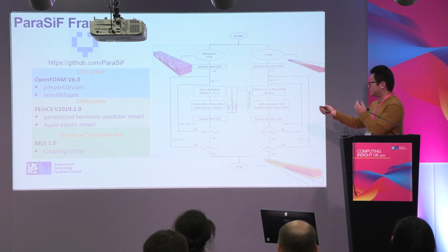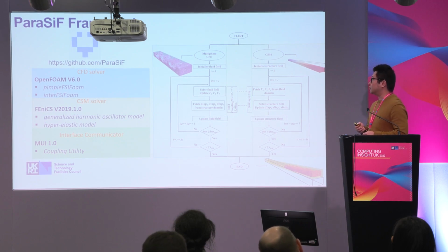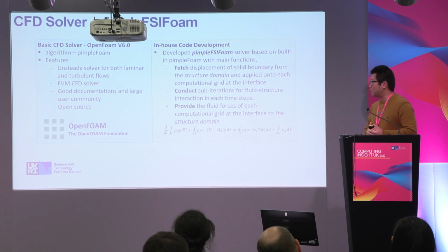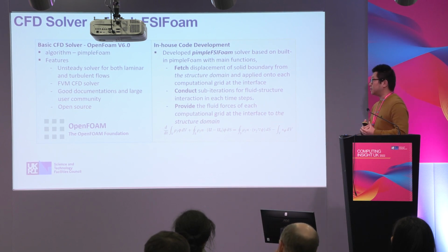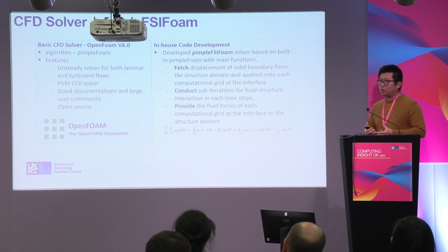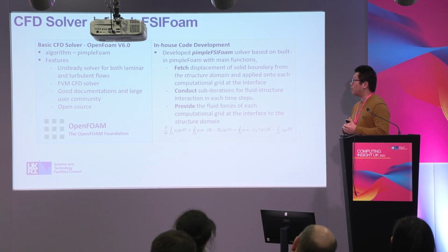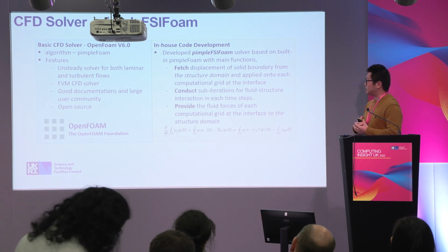We will go through the different elements one by one for the details. The first one is the left-hand side, which is the fluid solver. Currently, we use OpenFOAM implemented in the ParaSiF code. We have extended the built-in solver inside OpenFOAM that solves the incompressible Navier-Stokes equations.